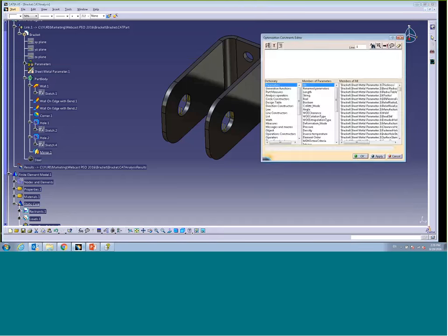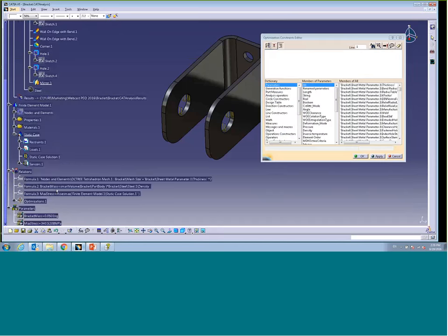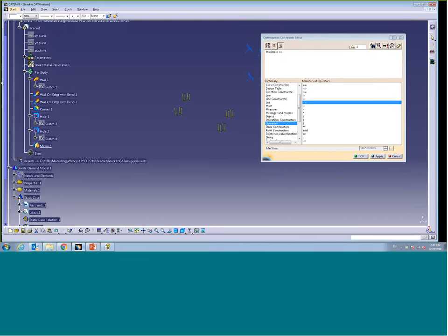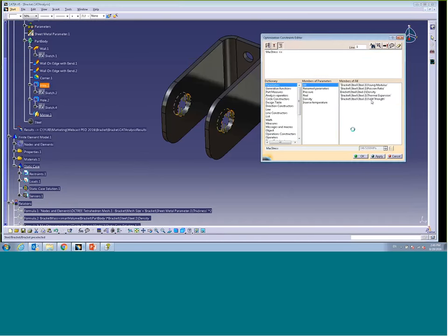Okay, so I want to make sure that my maximum stress is less than or equal to this. I'm going to put a filter on the material. You see there is a yield strength, just like that. So maximum stress should be less than or equal to the yield strength, or just plain less. It's up to me. Actually, I'll make it, let's say, like that, less.